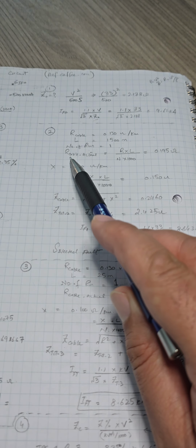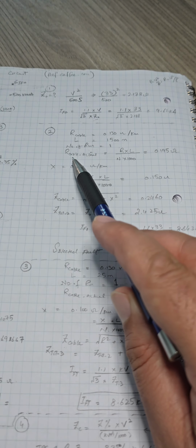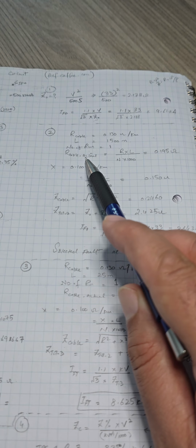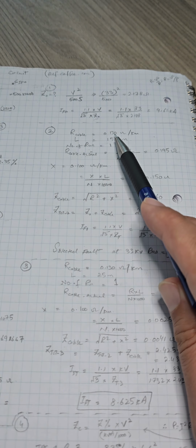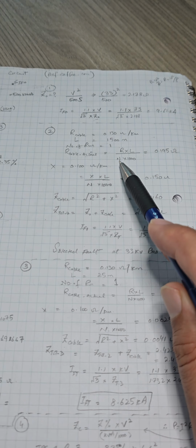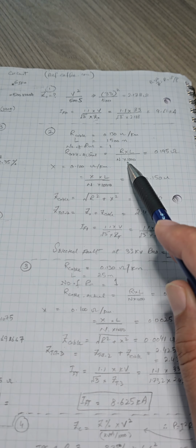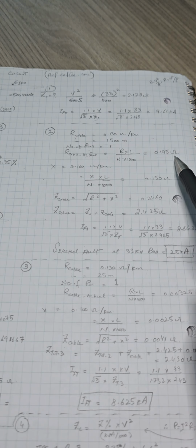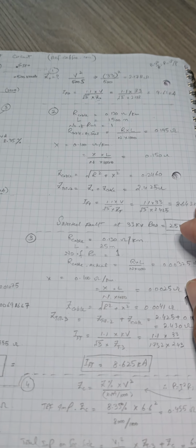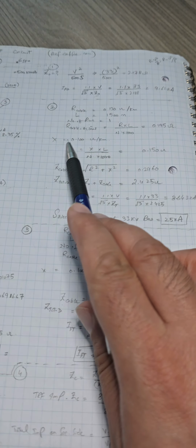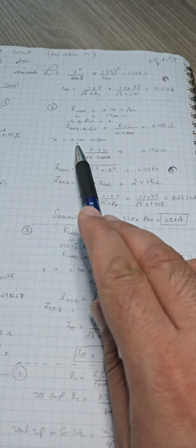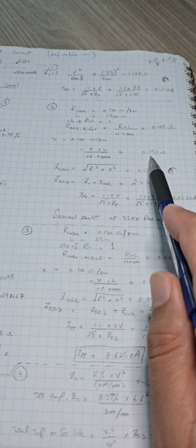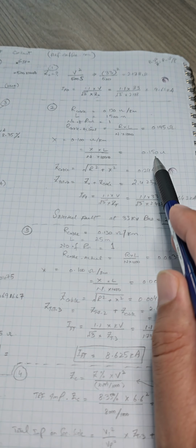And then we have to find the R cable, the actual resistance of the cable. Actual means by considering the length. So we have to multiply the resistance with length, divided by number of runs, multiplied by 1000. So we will get this value. Similarly, we have to calculate the reactance exactly in the same way. You can find the reactance from the data sheet, and we found it to be 0.15.